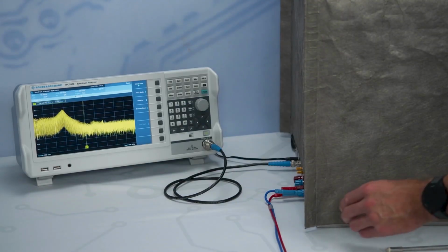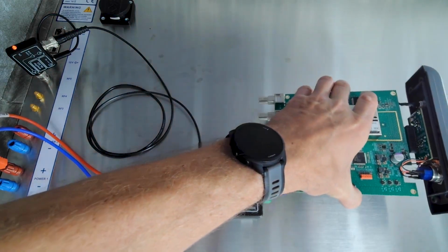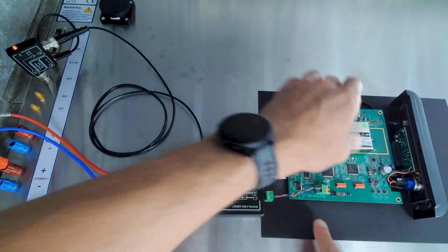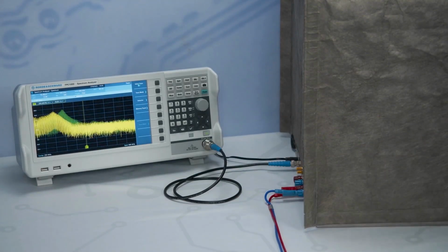And you can see now, if I change the distance and the parasitic capacitance, so I bring now the electronic closer to the reference plane and close the tent again. Now you can see here that this resonance is shifted down to 100 MHz. I put the trace before here in the memory trace, so that you can see the older curve in green and the new one in yellow.